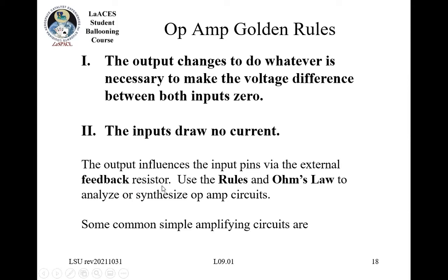So the way that you do this is you have to have some sort of feedback resistor that will connect that output back to one of the inputs, because otherwise how is changing the output going to affect the voltage at one of those inputs?